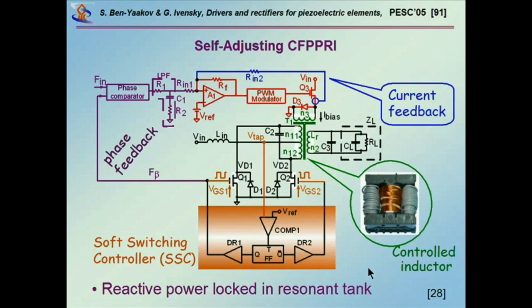So what we can do is use a control inductor that we can bias at the outer rim. This inductor has a gap inside. There is no gap at the outside. And these are bias windings. So you can change the inductance by biasing this. The power involved is very little, although the current is a little bit high, but the voltage is very low because it's a short circuit. And when you do this, you basically change the inductance.